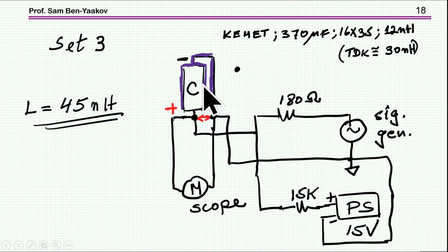Okay, there is some, as I've said, because of the way the current is actually penetrating the casing, but it's certainly not like having the plus here and the minus here. And this explains the fact that we are now getting 45, a lower inductance than before.